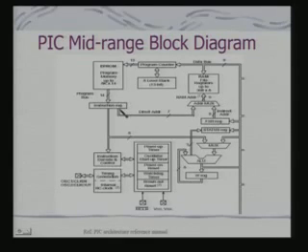This instruction register typically will have the instruction, and it will refer to the registers for operation. So that's why you find a bus connecting this part of your instruction register to the address multiplexer, through which the register gets selected for any kind of arithmetic operation.